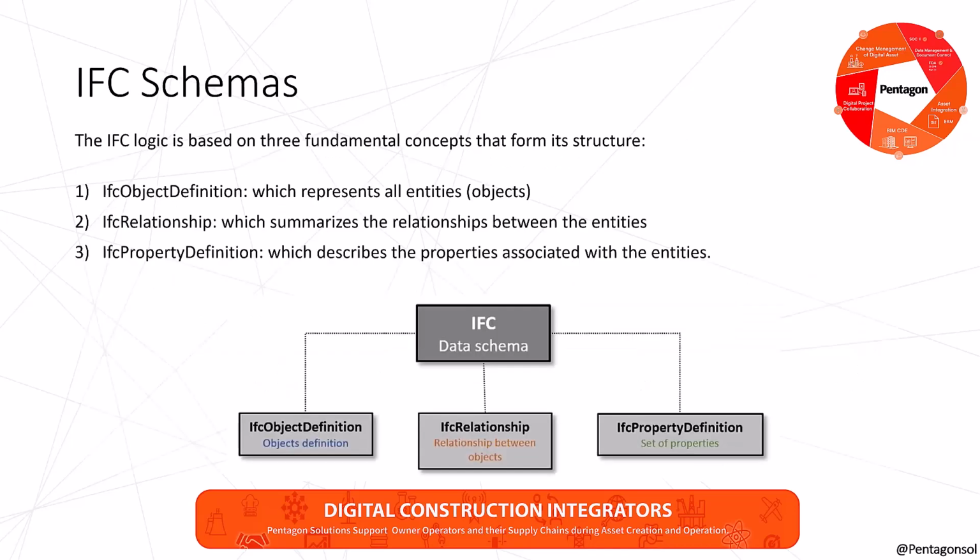This is just a brief now on different data schemas and their relationships within the project. IFC object definition represents all entities. IFC relationships summarizes these relationships between the entities. An IFC property definition describes the properties associated with these entities. Stephen will now walk through how IFC object definition plays a critical role in the IFC structure.